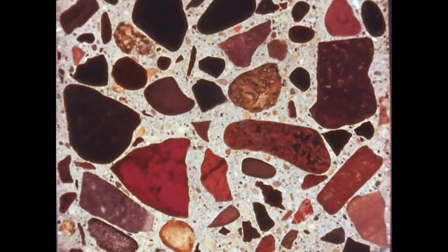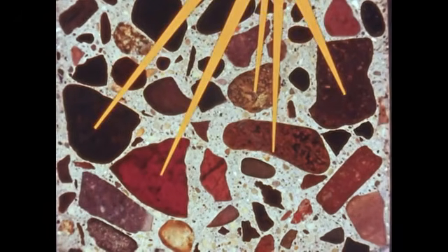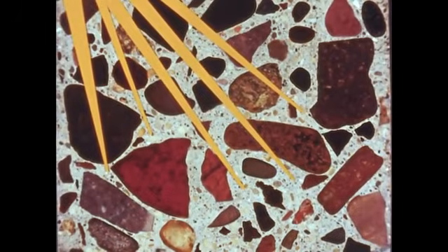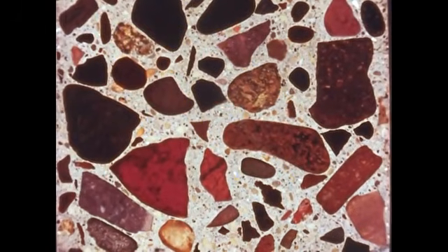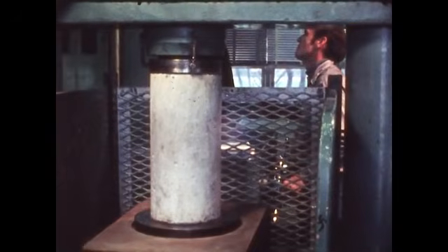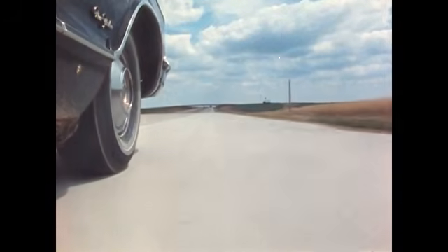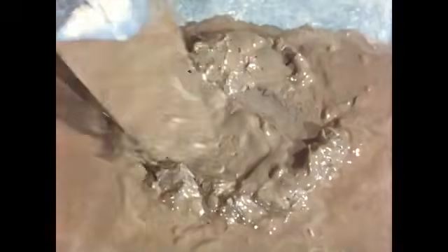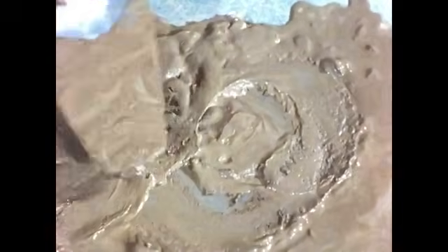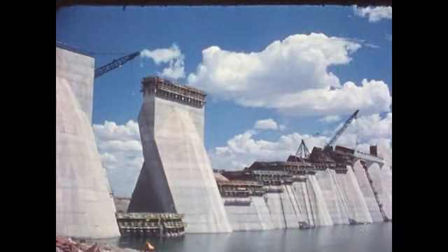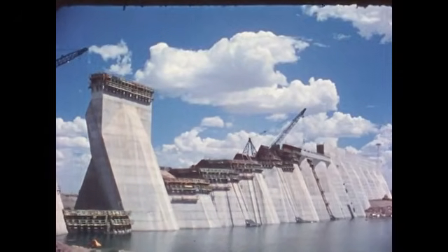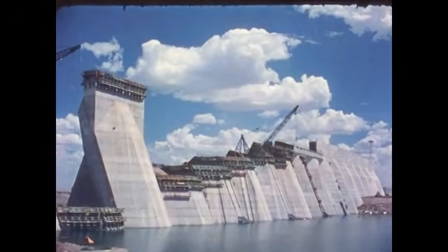Good concrete is a combination of sound aggregates bound tightly together by the hardened cement paste. As the aggregate is essentially inert, it is the quality of cement paste acting as a binding agent that largely determines the strength, water tightness, durability, wear resistance, and other desirable characteristics of concrete. Cement paste is a blend of Portland cement and water, which forms a semi-fluid paste that eventually hardens and binds together the aggregate in the hardened concrete mass.